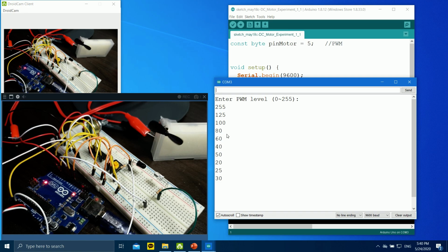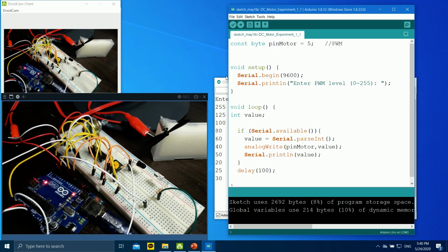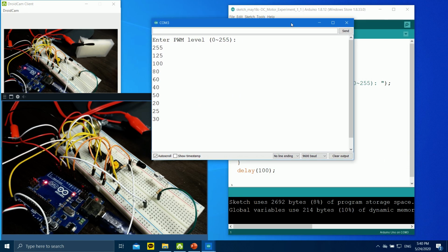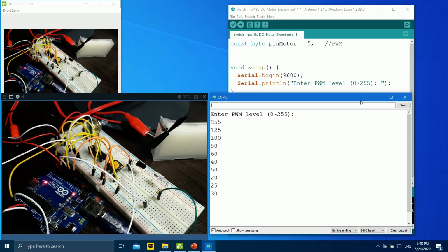Okay, this is the PWM basic principle when you drive directly using pin 5. But actually this one is not recommended, as long as your motor has a low power rating, I think it's fine using the timer pin directly as the output.